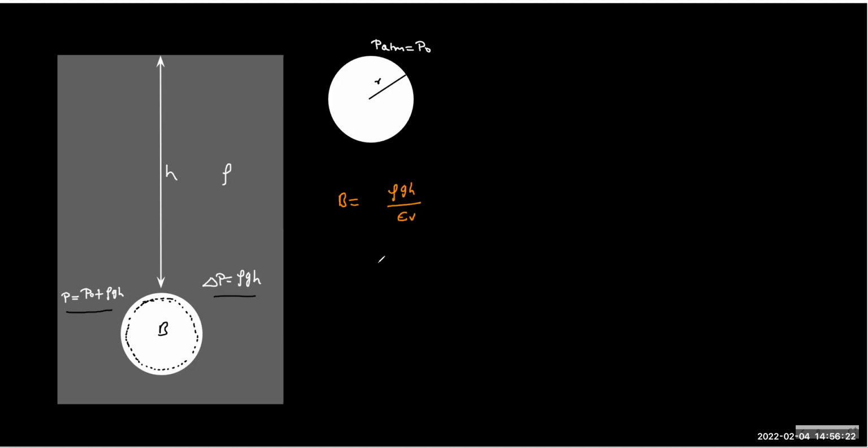So I will just add sigma V. You can say sigma V turns out to be how much? And sigma V is basically dV by V, with a minus sign. And for a sphere, because volume is 4 by 3 pi r cube, dV by V can be replaced by 3 times dr by r.